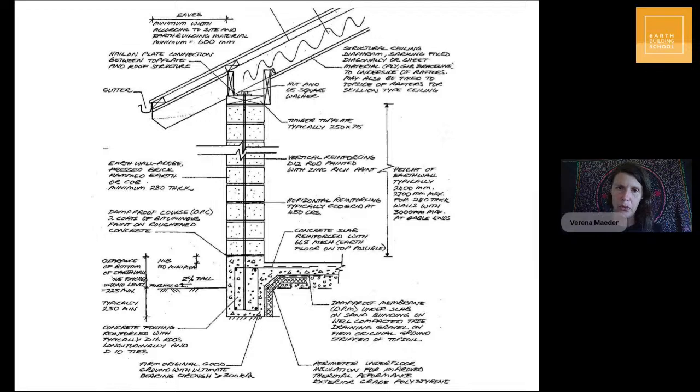You can do a thing called a penetrometer test, where you see how easy it is to get a rod into the soil. And there's different ways of just assessing whether your soil is strong enough. You have to really make sure that foundation doesn't slump under the weight.